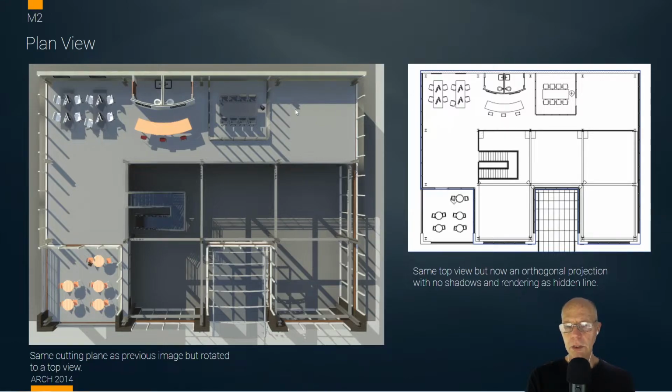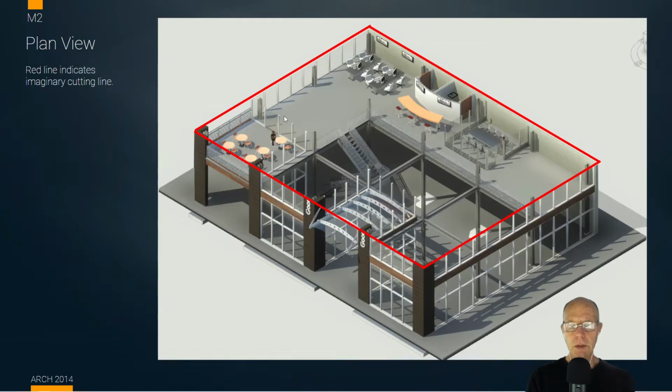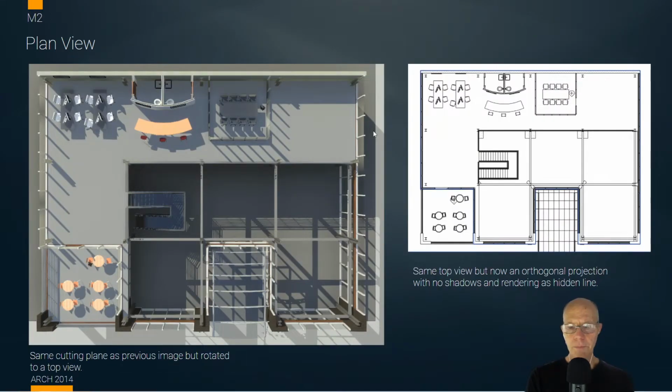And so it's just important to note, and I'll go back to this slide, that typically when we look at a floor plan, we're cutting through the room at the 4-foot level and only including things from 4 feet down. And we pick 4 feet because that's above the level of countertop height. So that allows furnishings to show within the drawing that we're creating.